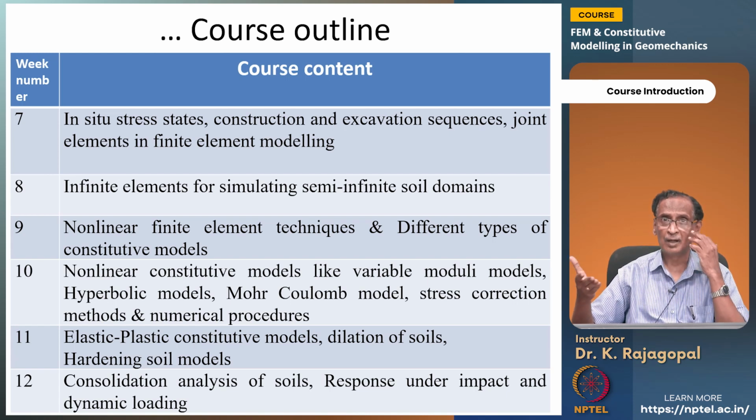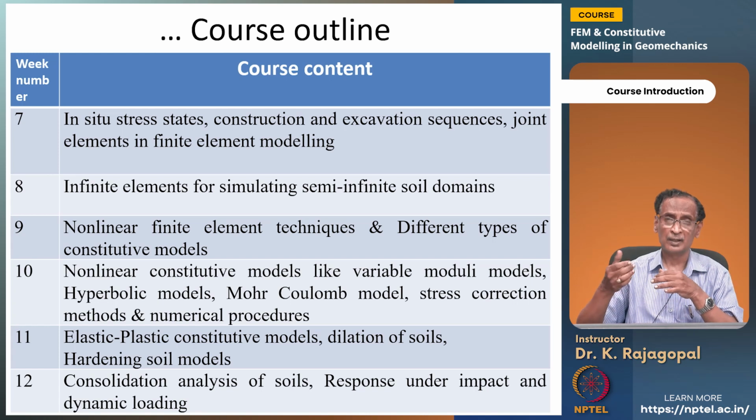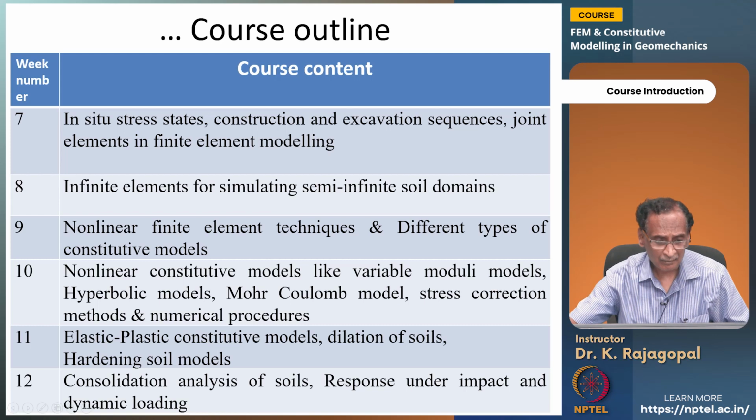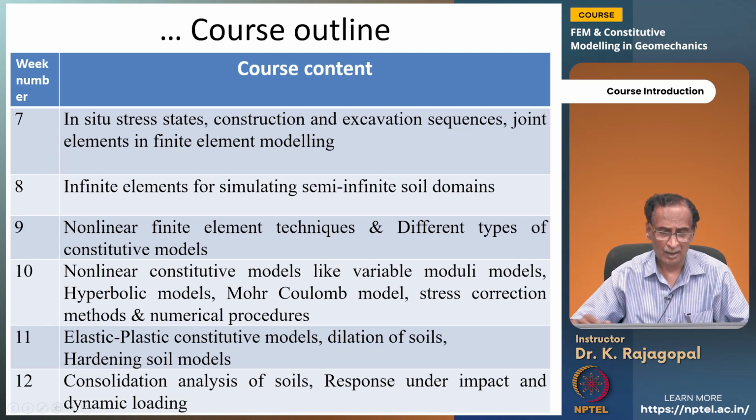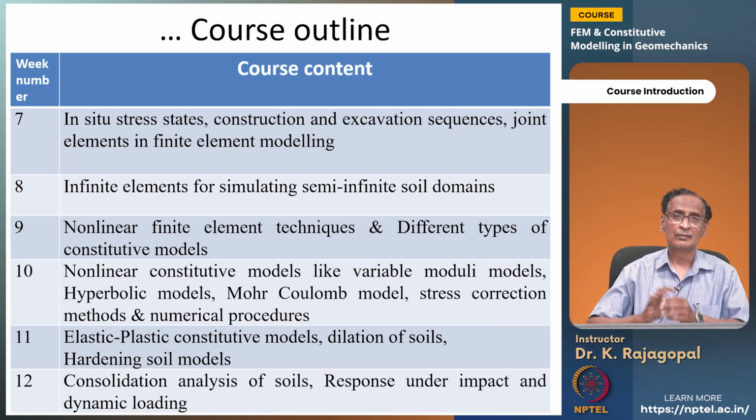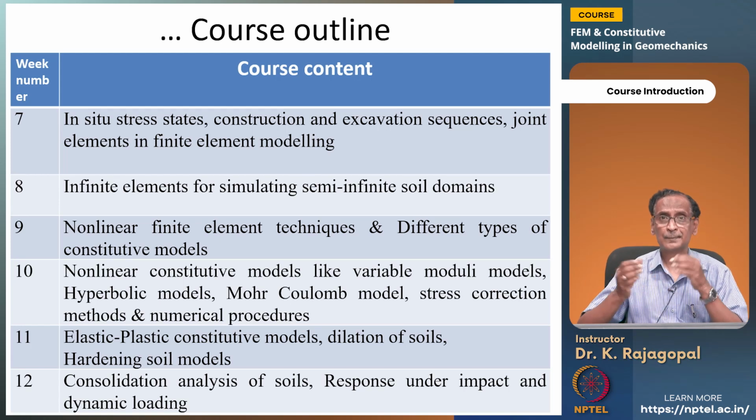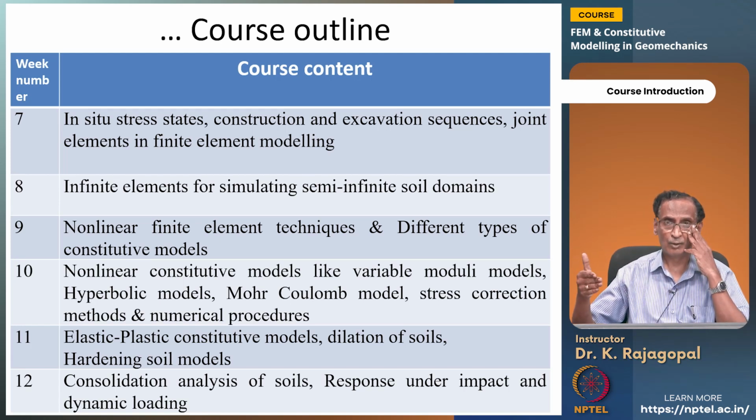But then the soil, we know, even if you apply some shear strain, like for example in our direct shear box test, we could get some volume expansion, especially when you have a dense sand or highly angular soil particles. Then we need to have some hardening soil models which differentiate between the loading and unloading paths and so on.